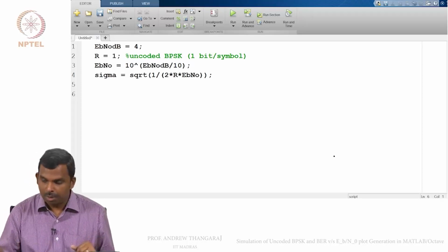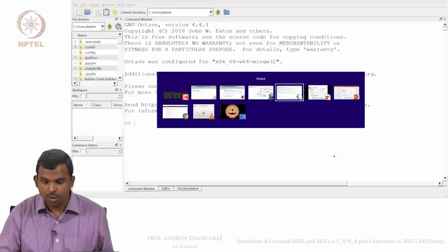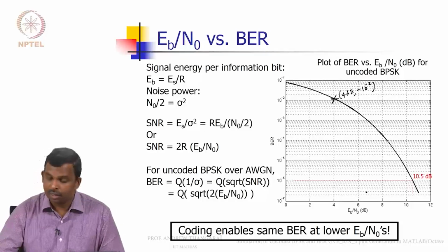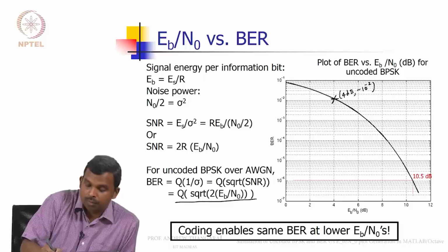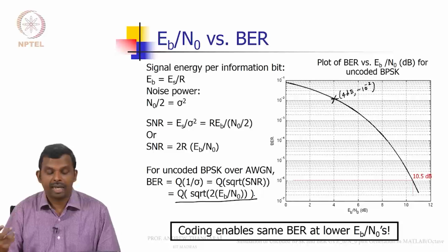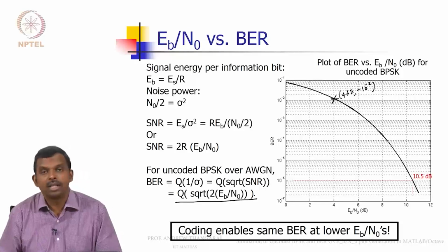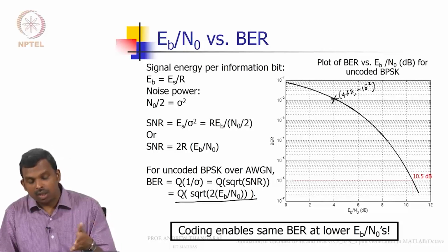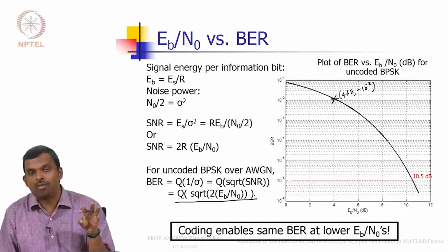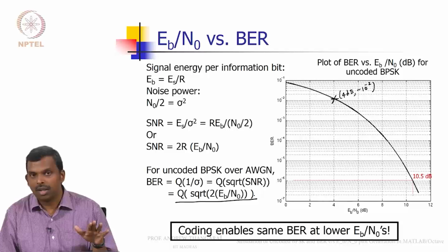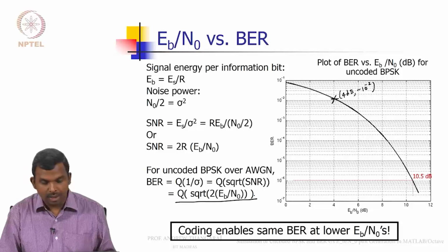Okay. So, now if you remember the value for bit error rate as a function of Eb over N0 is given by this formula, right. It is just Q of square root of 2 times Eb over N0, right. So, once I have Eb over N0, I just have to plug it into this and get my value for bit error rate, but I know my Q is implemented as 0.5 ERFC of x by root 2. So, if I combine those two, I will get my value.